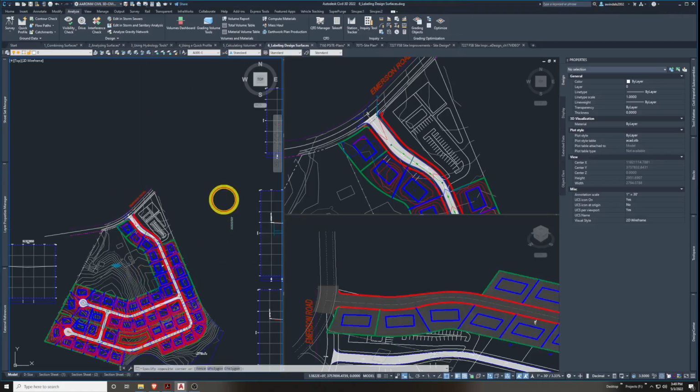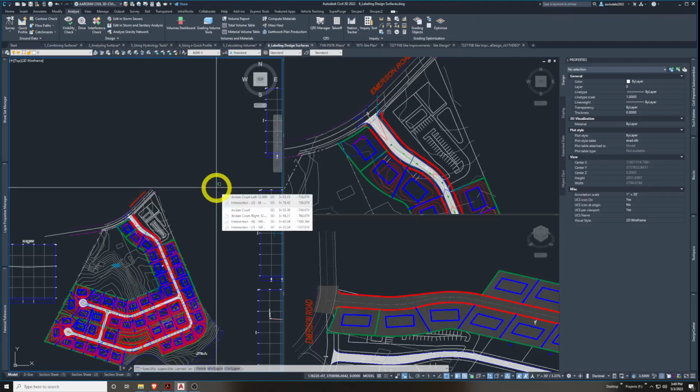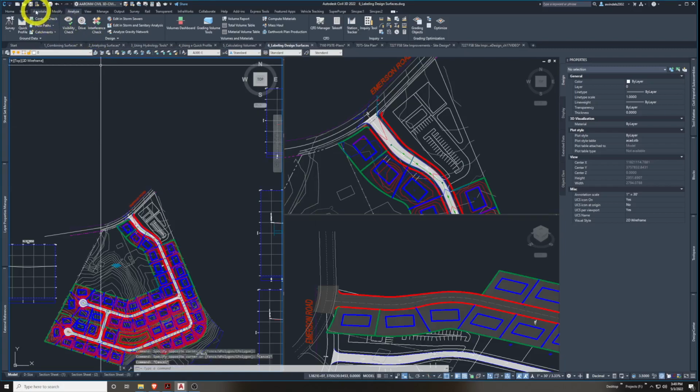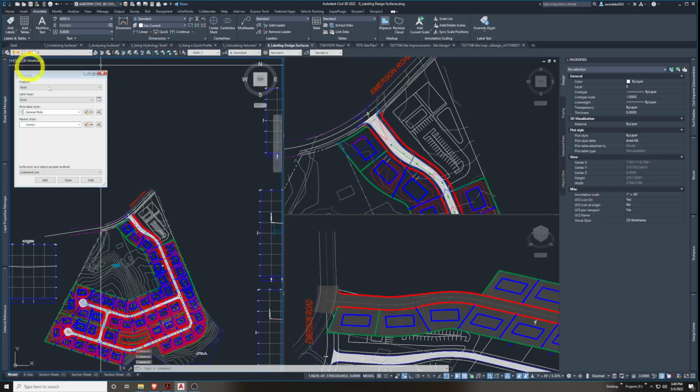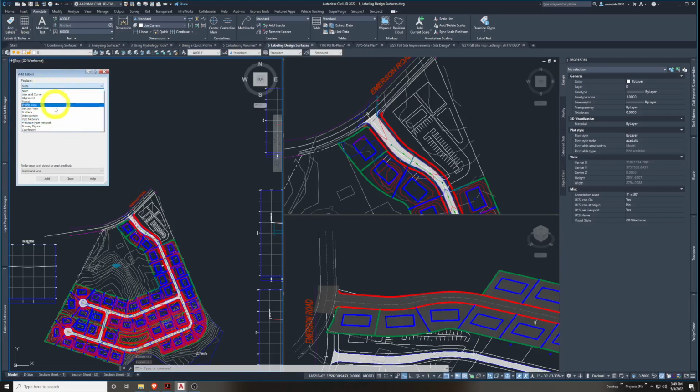So let's wrap this chapter and book up here on this last section: labeling design surfaces. Once again, when we get up to our labels, you can always go to our annotate home space there and click on this ribbon to go to annotate any Civil 3D object, and you can pick which object here. In this case, I'm going to go to surfaces, and we got our options.